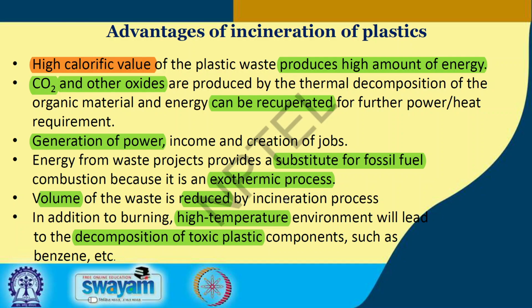Yeah. So the advantage of incineration is we can get high calorific value and produce a high amount of energy. Because plastic and papers have high calorific value, they are more suitable as a feed for a waste to energy plant. Then CO2 and other oxides are produced by the thermal decomposition of organic matter, and energy can be recaptured. Then generation of power, substitute of fossil fuels, and it is an exothermic process. If it were an endothermic process, we would need to supply energy, but it is an exothermic process that will produce energy, and the volume of waste is reduced by the incineration plant.